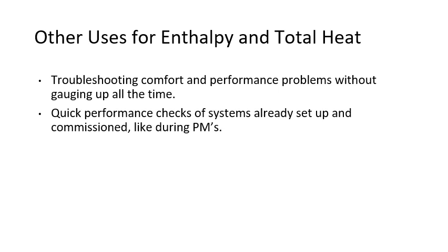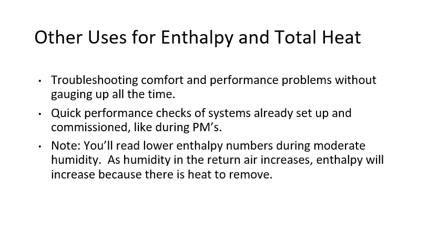Those are appropriate times to gauge up. But it may not be necessary to gauge up on every preventive maintenance call. Sometimes you can do a quick check of your enthalpy drop and your total heat, and you can determine that a system is performing correctly, and there is no need or no history that's going to require you to gauge up and look any further.